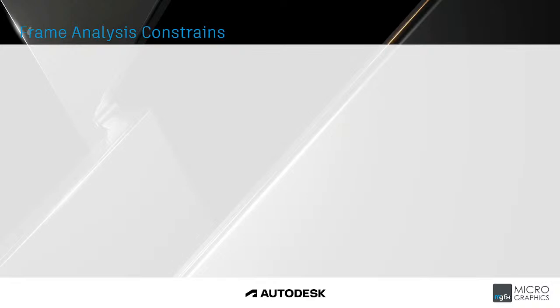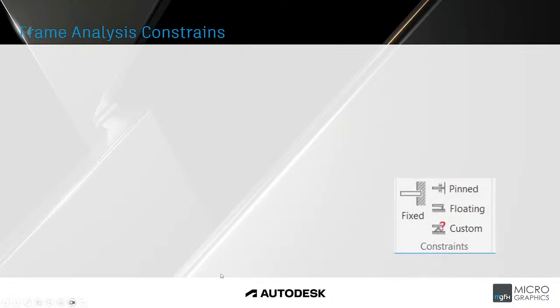So your frame analysis constraints, so you do get different constraints that you can use when inserting frames. So I'm just going to have a look at some of the different constraints you do get. As you can see, you get your fixed, your pinned, your floating, and your custom constraints. So what's the difference between using these constraints? So let's have a look.